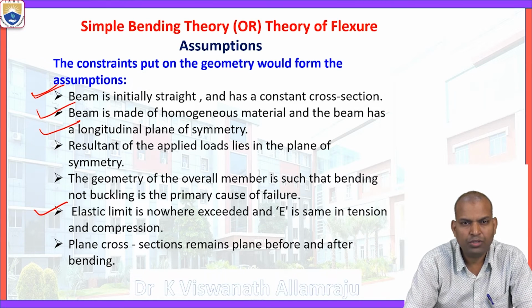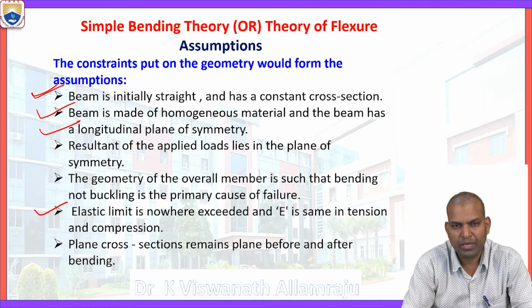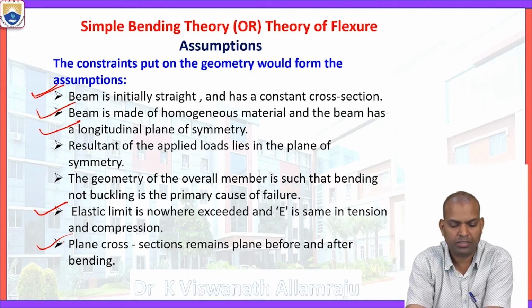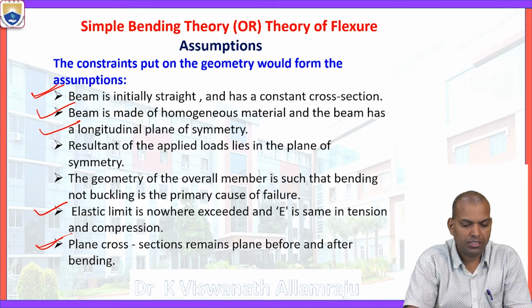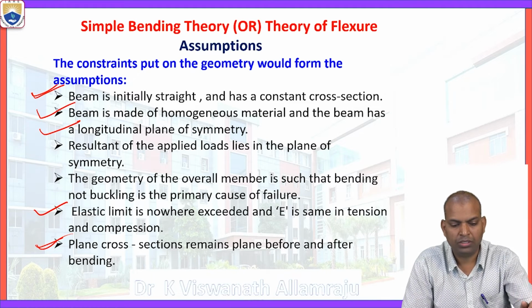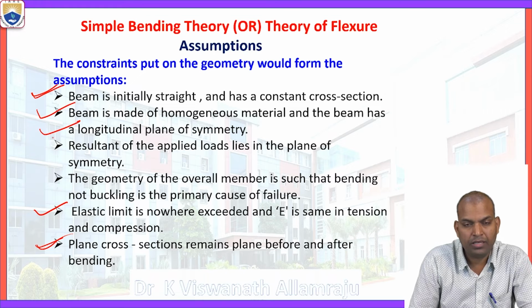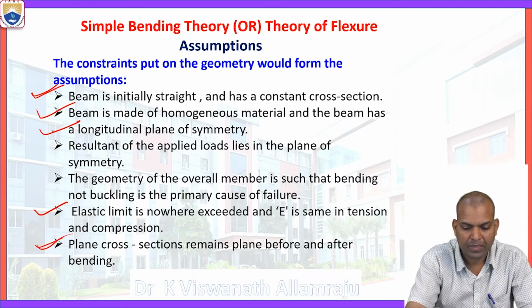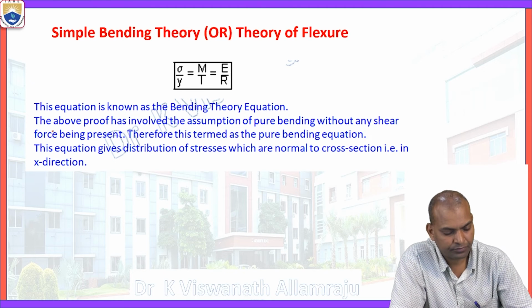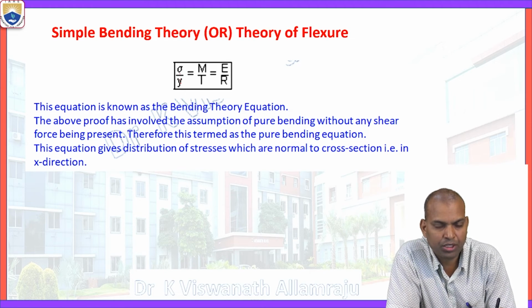And also the value of modulus of elasticity remains the same both in tension and compression. And one more, the plane cross sections remain plane before and after bending. These are certain assumptions we follow in order to derive the bending theory.